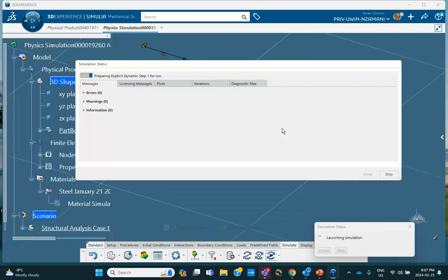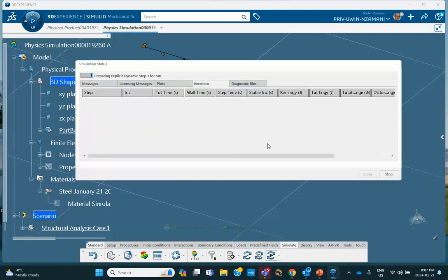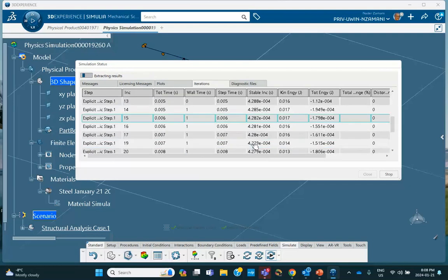Ordinarily in dynamic analysis, I think the implicit displacement is automatically generated, but okay, so it's not here. So here is the iteration. So notice that there are several things that I did here that were unnecessary. One is that meshing, I did it the long way. Then I didn't join it, etc. Then when I ran it, I forgot to ask for displacement, so I had to go back and ask for displacement and rerun it. It's going to be done. Extracting results.